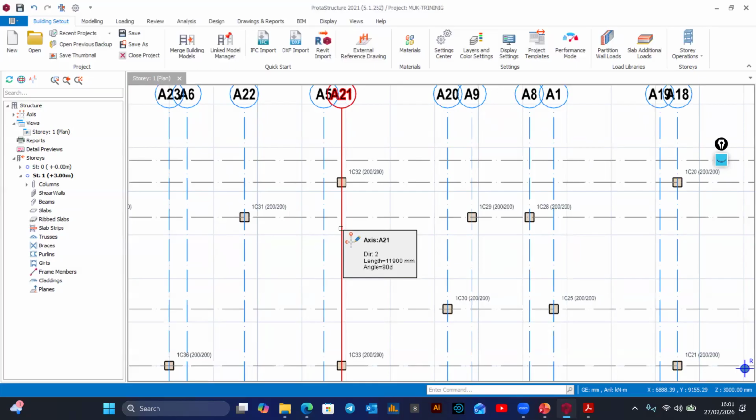Now, the name which we gave in AutoCAD was for a layer, remember, structural column. It was for a layer where we were going to place those columns. You could have noticed that at the point of importing them using a DXF file, that layer which you activated first was the layer called structural column. So it comes right from AutoCAD, and then it is recognized in ProtaStructure.